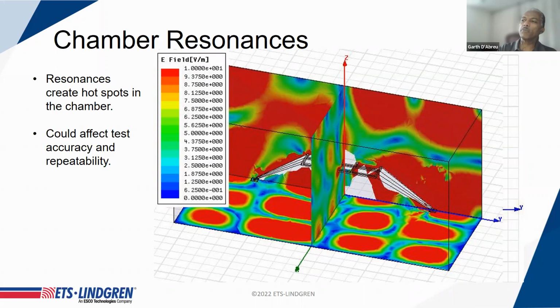The other one, which was a little more complicated, is the fact that you were trying to drive this device with several tens of kilowatts of RF power. And of course, what the amplifier sees as you change frequency is a series of intervals of going through very high VSWR peaks, which result in the amplifier folding back to protect itself, as it's trying to drive energy into this very high impedance and highly mismatched load. So that became another knock-on problem with trying to use this device for that type of measurement.